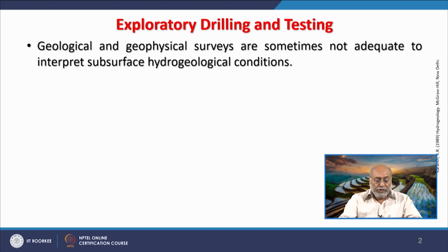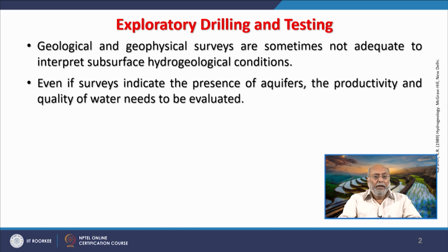Now, geological and geophysical surveys, as just mentioned, are sometimes not adequate to get the complete subsurface hydrogeological conditions of an area. In that case, we go for exploratory drilling. Even if surveys indicate the presence of aquifers, how much yield there would be, and what the productivity and quality of the water is going to be, also have to be evaluated, and that is done through exploratory drilling.